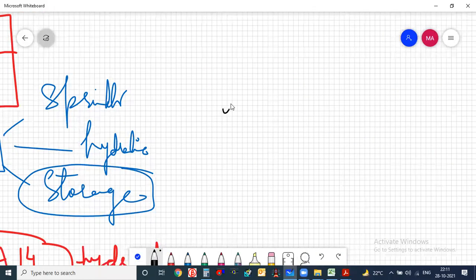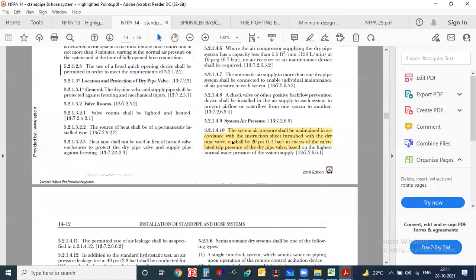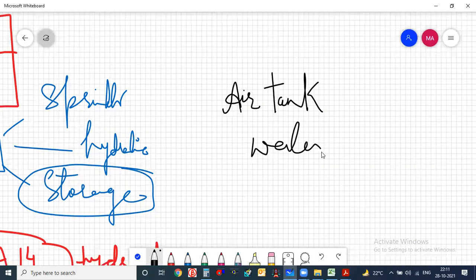we use one more piece of equipment actually, one air tank in the firefighting system. It is sometimes called a cushion tank or something. So this particular point is talking about that system only. Whenever we are talking about the water system, we should have at least one system to remove the air. Whenever water is flowing in the pipe, there may be chances of entrapment of air. This is 100%, there will be chances. So that's why it is called a cushion tank, I think.